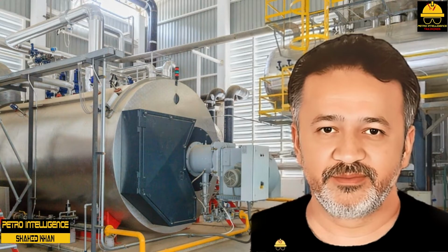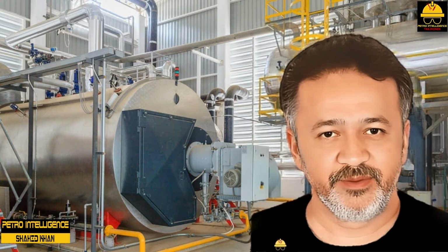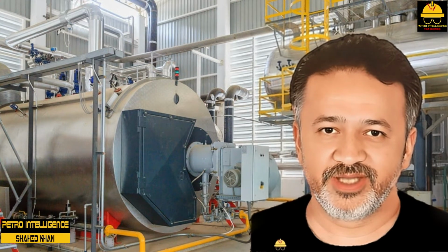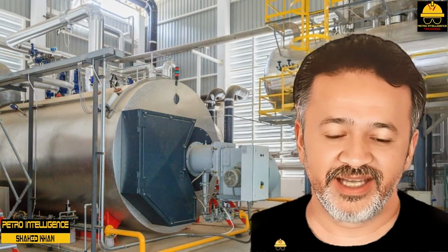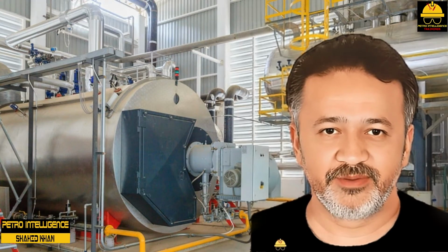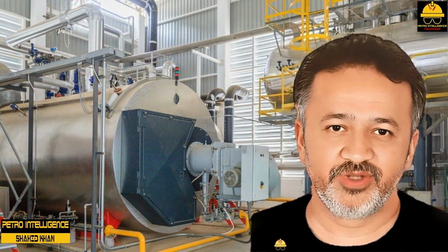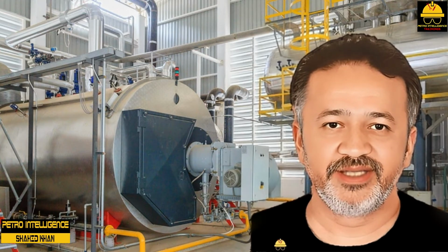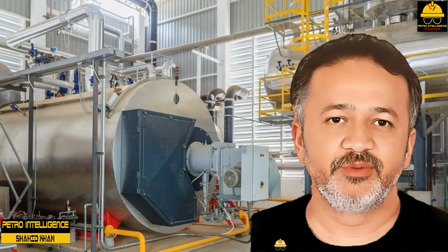Fire tube boilers. A more complicated boiler is the fire tube boiler, which resembles a modified shell and tube heat exchanger. This type of boiler is composed of a shell and a series of tubes designed to transfer heat from the fire tubes and into boiler feed water. Combustion gases exit through a chamber similar to an exchanger head and pass safely out of the boiler. The water level in the boiler shell is maintained above the tubes to protect them from overheating. The term fire tube denotes that the heat source is from within the tubes.